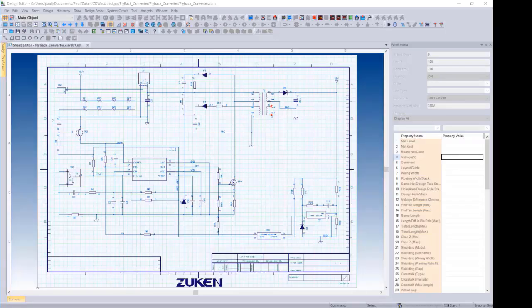So this is the first part of the demonstration, schematic capture stage. I'm going to assign net voltages here. I'm going to create class-to-class rules, and I'm going to import master design rules. And then I'm going to show you how you can assign nets into a particular net class efficiently. And then I'm going to close this, forward annotate the changes into my PCB, and then show you how you can check it there. So the first part, I'm going to add some net voltages.